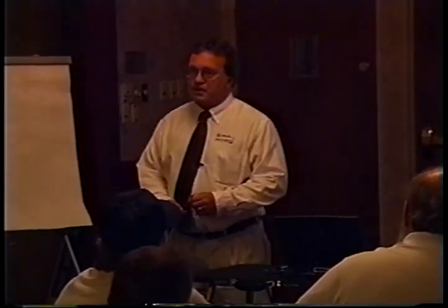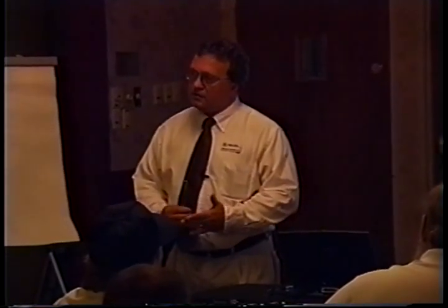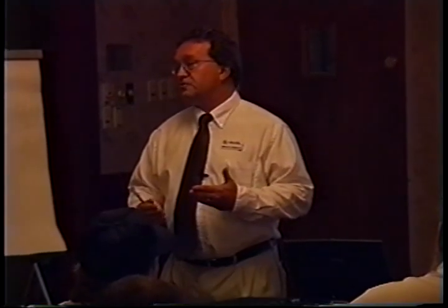There has been some study down at Ohio University done by one of the professors there that has shown that maybe your moisture is less at those joints if you don't seal them. Maybe it allows the moisture to escape through the joint, I don't know. But we're starting to see some indications that it might not be that serious of a problem as we thought. Particularly with your shorter joint spacing, you're not getting the expansion and contraction distances in those joints, because you're spreading it over more joints.